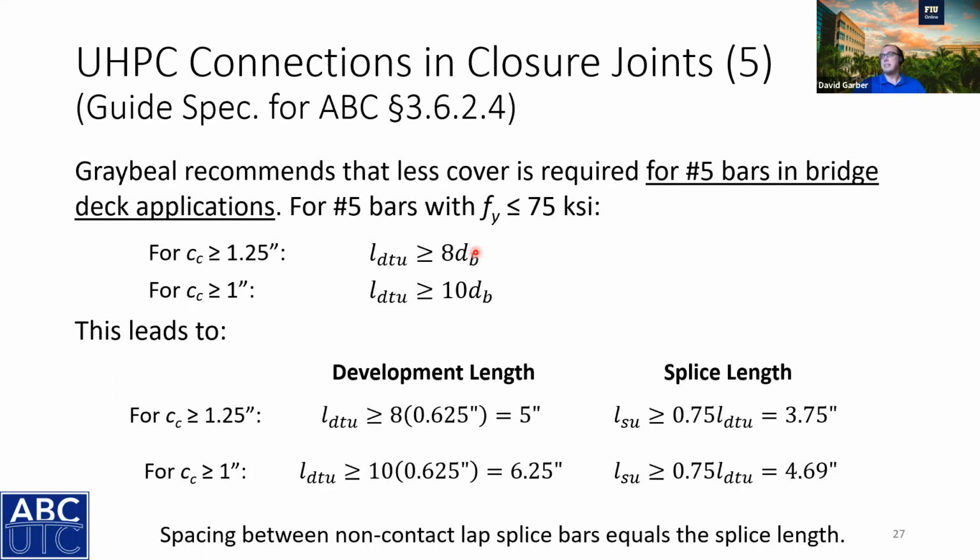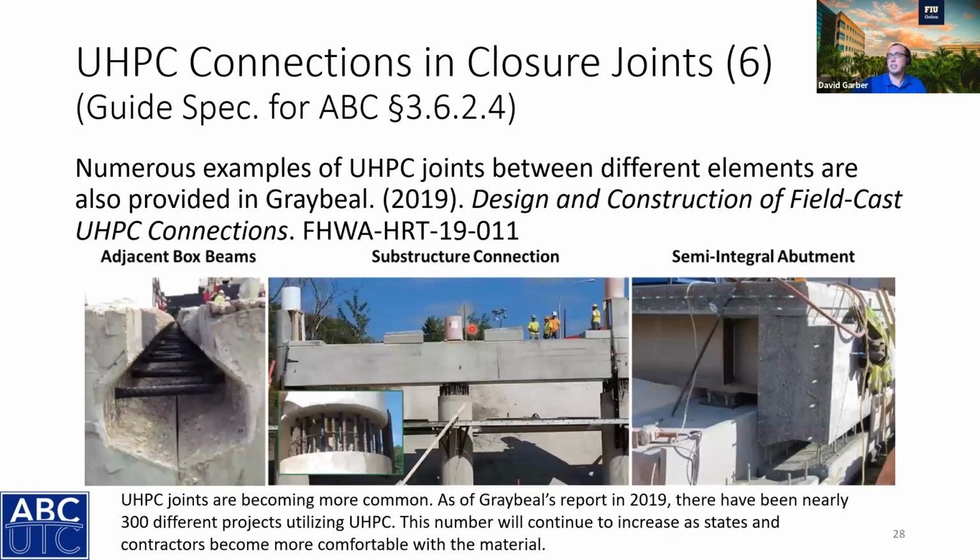Graybill also has some details specific for number 5 bars. So number 5 bars are commonly used in bridge deck applications. So he did some testing, and you can decrease your cover and still have 8 db or 10 db development lengths. So I just highlight that there.